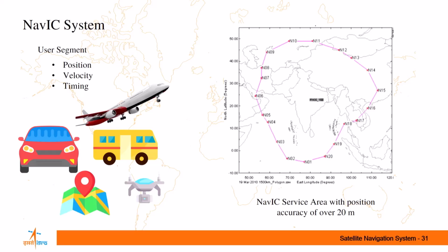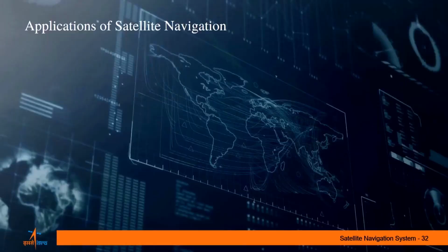Whichever GNSS system we use, whether it is Navstar GPS, GLONASS, Galileo, BeiDou, IRNSS or QZSS, it is preferable that maybe we can check our observations during afternoon while processing the data. The processing software provides us flexibility to remove such observations from the processing, so that will provide us a better solution.